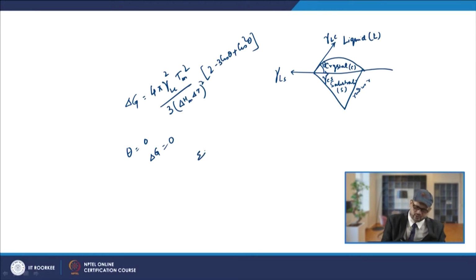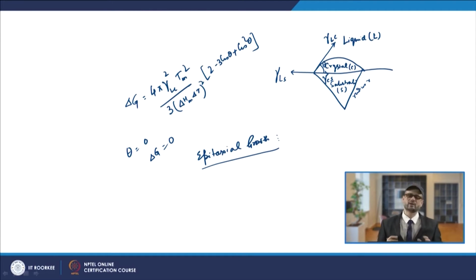So, this epitaxial growth is normally, referring to the example of the autogeneous type of welding process. In these cases the growth mechanism will be known as epitaxial growth, or the nucleation also, which is occurring on the pre-existing grains which are working as the nucleation sites. So, that will basically be the epitaxial nucleation.